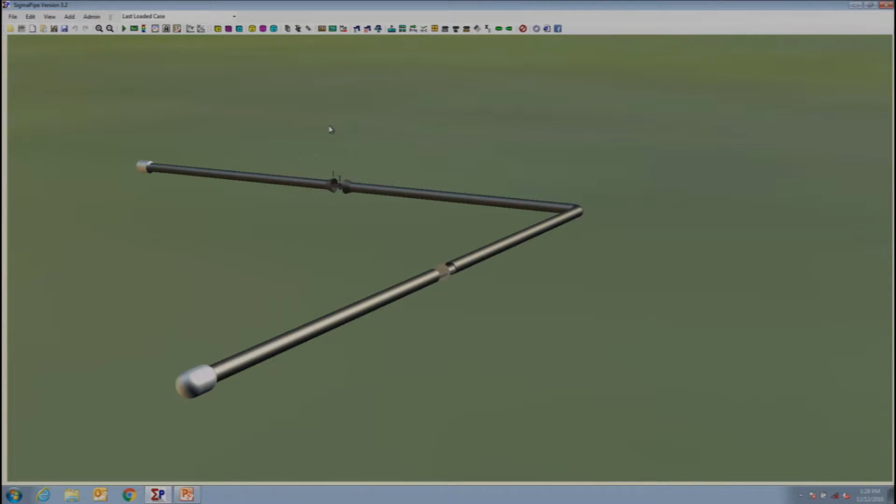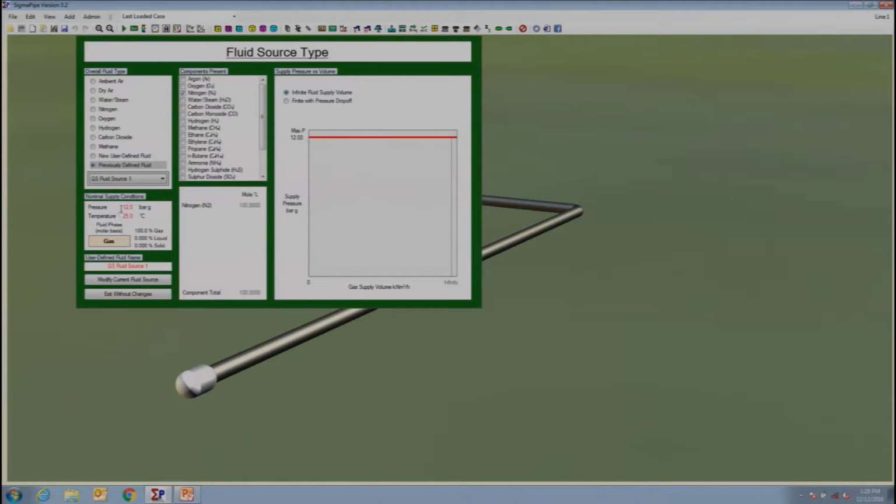Okay, so that's about as far as I wanted to go on the critical flow side of things. So now I'll change gears a little bit. I'll make the gas hot and low pressure, and then we'll see some of the thermal behavior of this thing. So the first thing is, if I edit the gas type and I say, no, look, I don't want 12 bar. Let's take it down to 0.2 bar, but 600 degrees in this case. And just for fun, let's add some water and carbon dioxide in at 10% each. So we're just making effectively a kind of flue gas. You can add whatever you want in there.